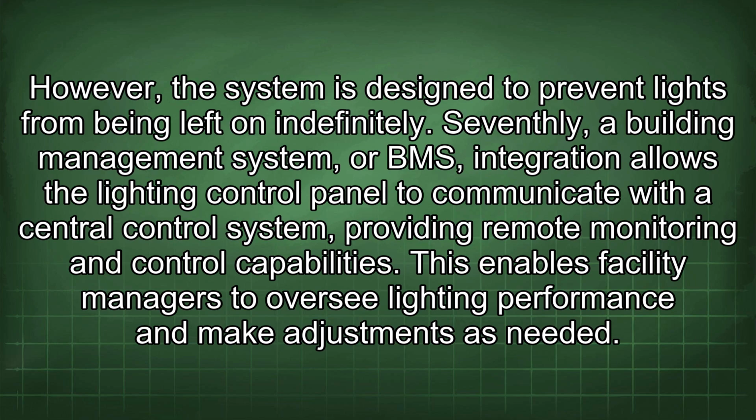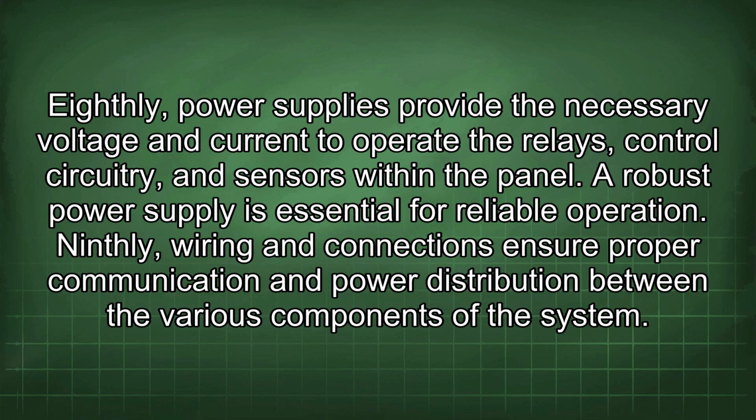Seventhly, a building management system, or BMS, integration allows the lighting control panel to communicate with a central control system, providing remote monitoring and control capabilities. This enables facility managers to oversee lighting performance and make adjustments as needed. Eighthly, power supplies provide the necessary voltage and current to operate the relays, control circuitry, and sensors within the panel. A robust power supply is essential for reliable operation.